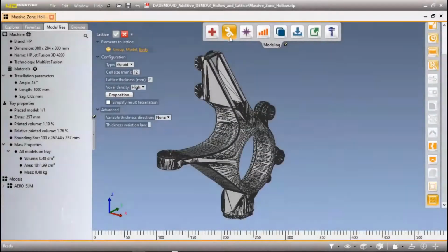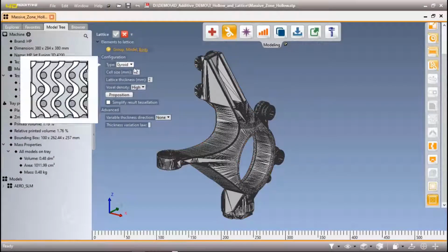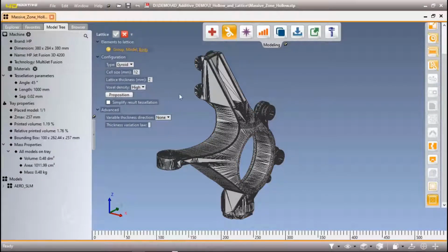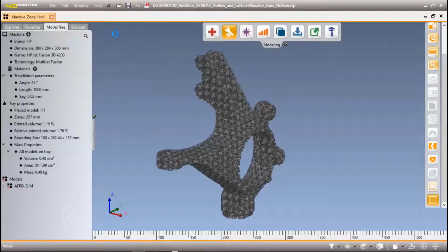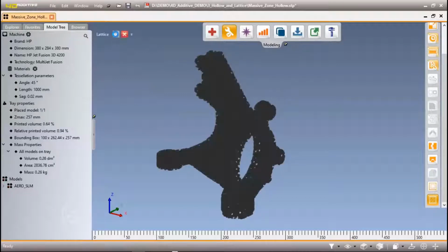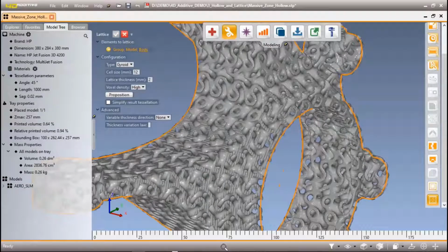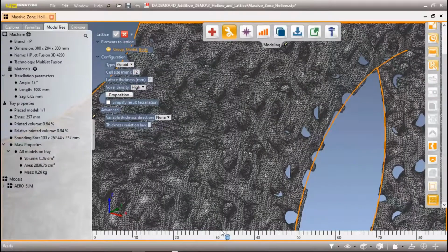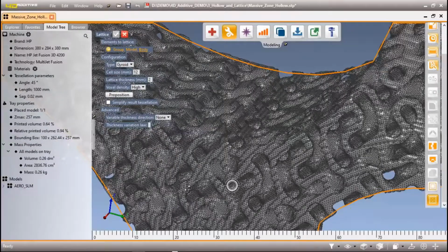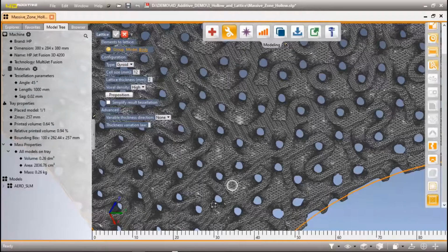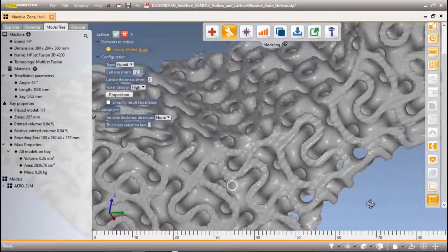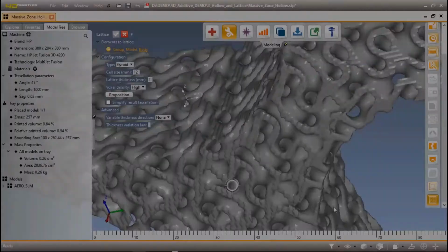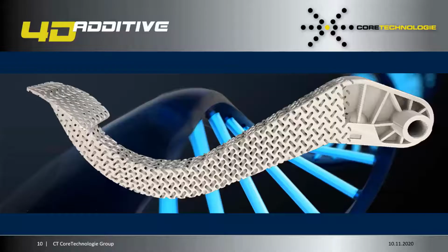So based on that file here, as in the previous video, the gyroid will be created really quick, because then you have this really lightweight model. If you check on the left hand, the mass of 480 grams will be dramatically decreased to 260 grams. So in mass, in the left hand. Without edges view, you see really the structure of this grid.